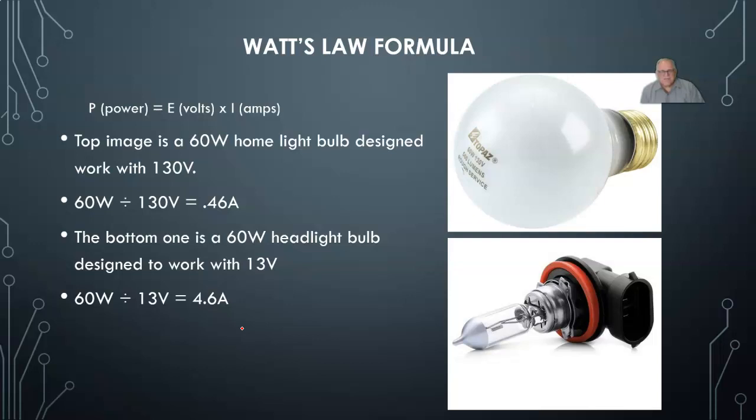This is the reason that in the mid-50s, the automotive industry switched over from 6 volts to 12 volts, as they can use smaller wire and less amperage to do the same amount of work. The automotive industry has been discussing for decades going away from a 12-volt system to either a 24-volt or a 36-volt system. They never have done it, and now as we get more hybrid electric vehicles, we have our higher voltage. And you will not see an electric vehicle where the motor that's moving the car down the road is a 12-volt motor. So they're using hundreds of volts on that motor to move the car down the road because they can decrease the amperage.